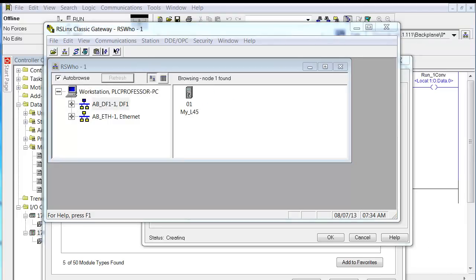Okay, I paused the recording just for a second, and I went over and pulled the RS-232 cable out of the L35E and plugged it into the L45. Now the L45 does have a COM port on the front of it. It has an RS-232 port. It just doesn't have Ethernet. Ethernet has to be gained with an Ethernet bridge card on the 68 backplane.